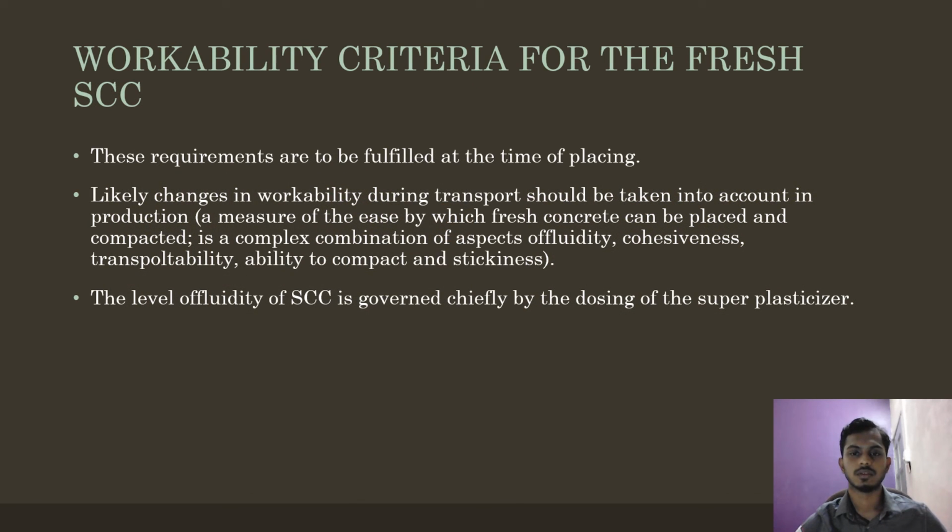Workability criteria for the fresh SCC. These requirements are to be fulfilled at the time of placing. Likely changes in workability during transport should be taken into account in production. A measure of the ease by which fresh concrete can be placed and compacted is a complex combination of aspects of fluidity, cohesiveness, transportability, ability to compact and stickiness. Third one, the level of fluidity of SCC is governed chiefly by the dosing of the superplasticizers.